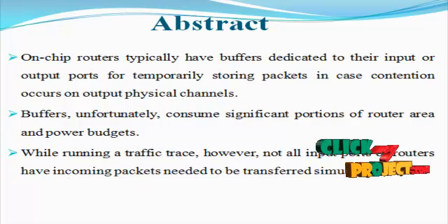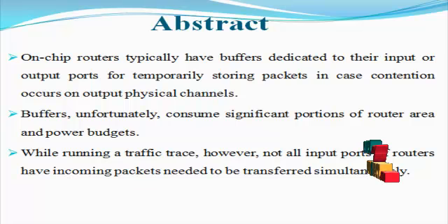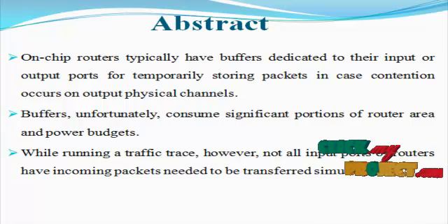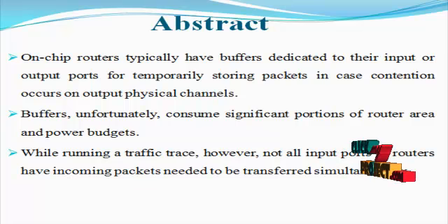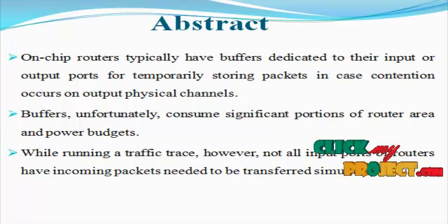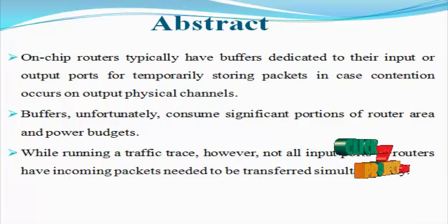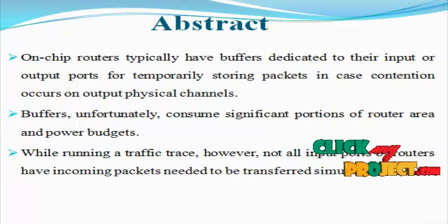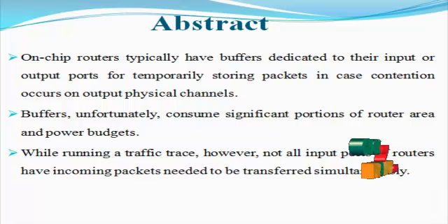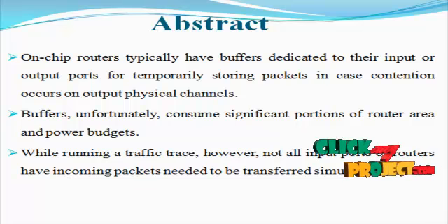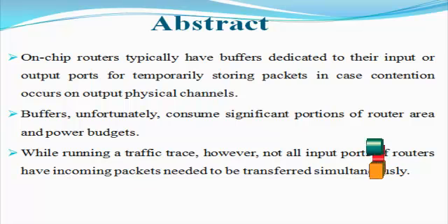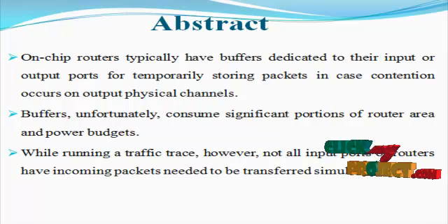Routers typically have buffers dedicated to the input and output ports for temporarily storing the packets, in case contention occurs on the output physical channel. Buffers unfortunately consume a significant portion of the router area and power budget while running the traffic trace. However, not all the input ports of a router have incoming packets to be transferred simultaneously. Therefore, a large number of buffer queues in the network are empty while some queues are mostly busy. This observation